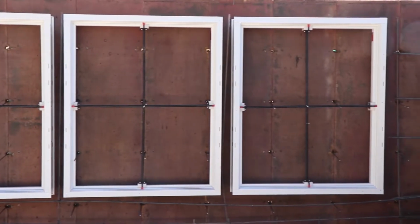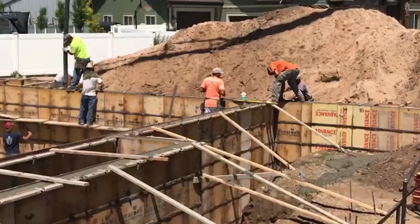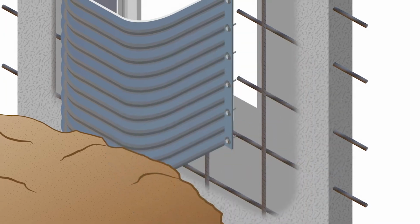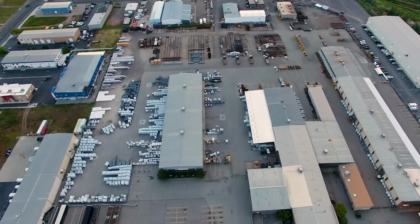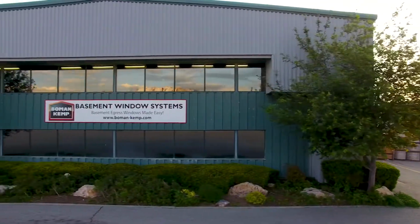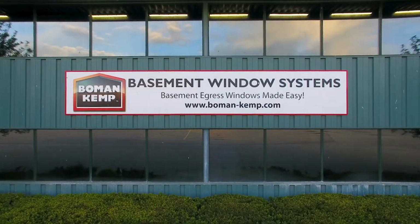With the considerable amount of rebar going into the foundation, this requires a little planning and inspection before the foundation is poured. If the buck or the attachment bolts end up touching the rebar, there is a high probability that a corrosion cell will be created. And number 2, conduct proper testing before and during the installation process to make certain that the buck, attachment bolts, and area well are not in contact with the rebar. Proper testing is ultimately the best way to ensure our products perform as designed and help you keep your customers satisfied.